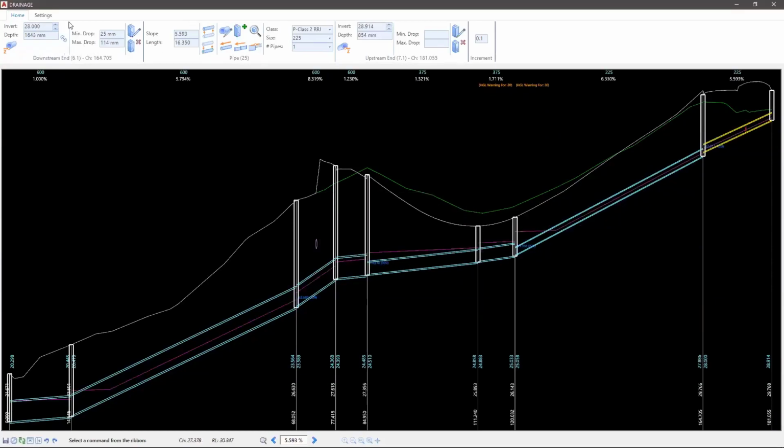One change that is brand new here is that this link icon pops up. Every time you make a manual edit to the levels or to the pipe, either end, you get this link. And it will actually tell you that you've manually modified the pipe as opposed to the automatic design. And that's great. It's a nice little visual warning, and I can still do my up and down edits for my pipe based on my increments. So down and up here, down and up here. I can change the increment, maybe go to 0.5 meter, jump it down.